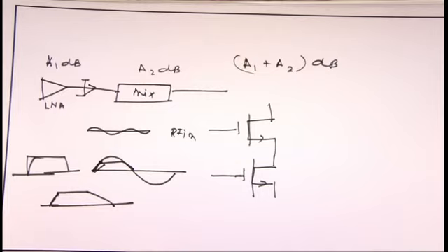But when I change it to the sinusoidal case, I should not expect any harmonics because it is the same frequency, omega LO minus omega RF. But still, if you take the DFT, you will get all those harmonics, because actually it is a large signal.